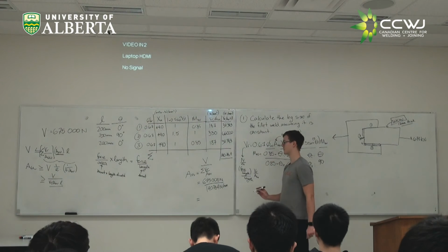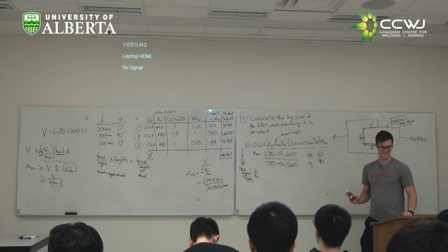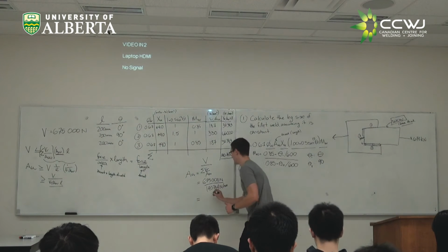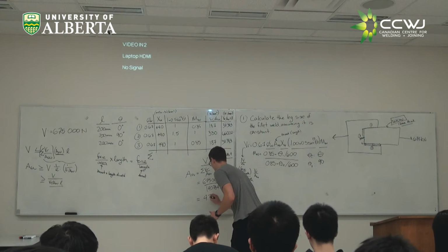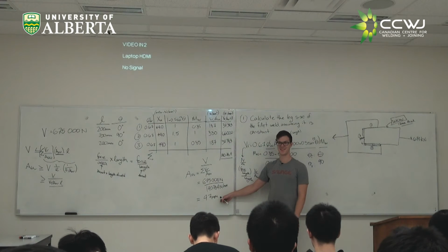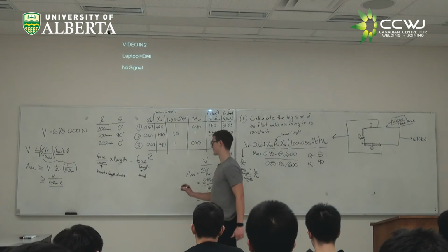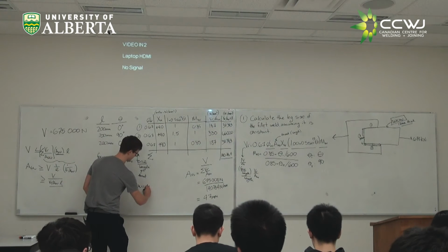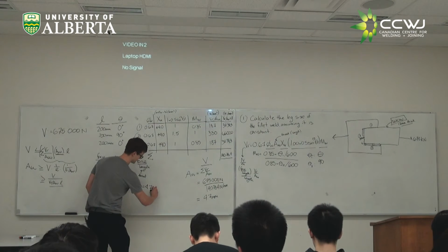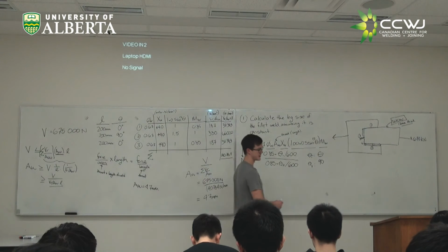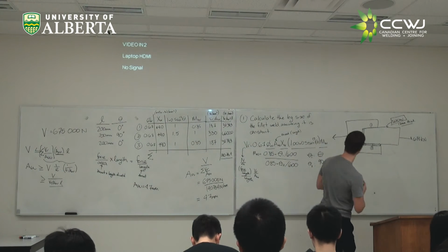What do we get for our required weld size? 4.7? Now, actually I misspoke there for a second. Is this our weld size? No, that's our weld throat, right? So if we have AW equals 4.7 millimeters, then I want to make sure I keep consistent with our notation here.